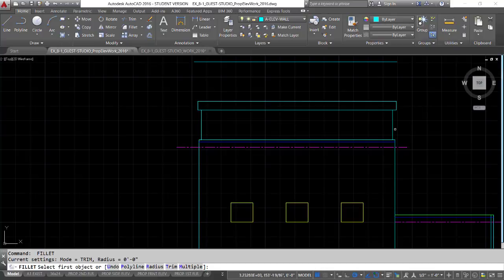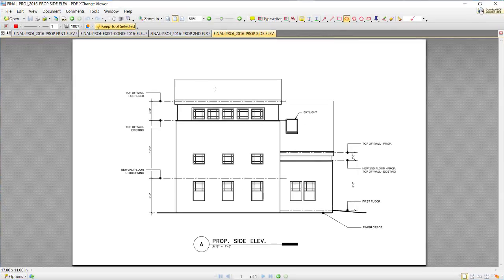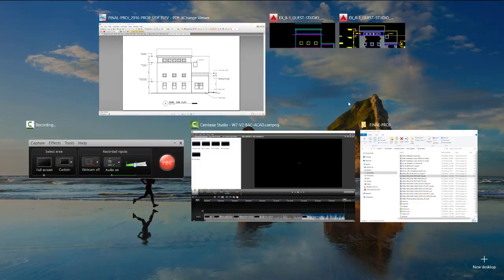And then we just need to draw the lines going up to meet the peak of the roof. And one of the things that you may notice on the handout is that these lines, as they slope away from us, have become quite a bit lighter than the actual eave line that's facing us on this elevation. So that's done by placing those lines on a different layer.